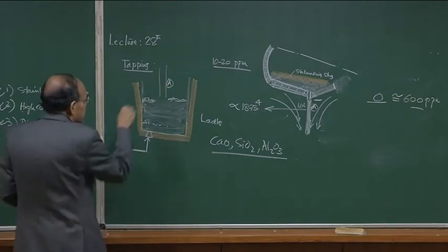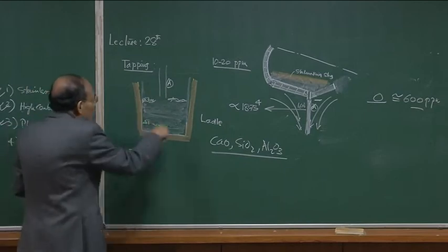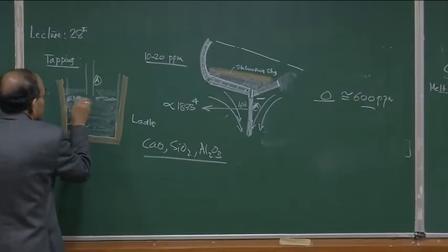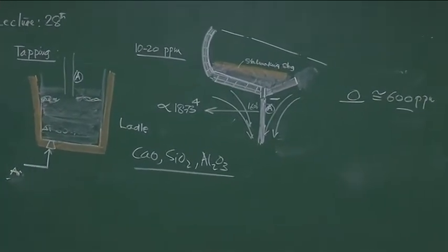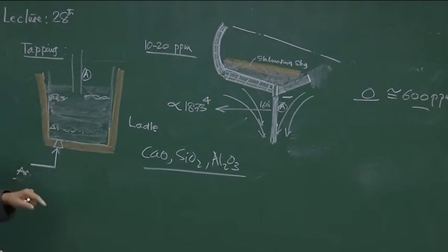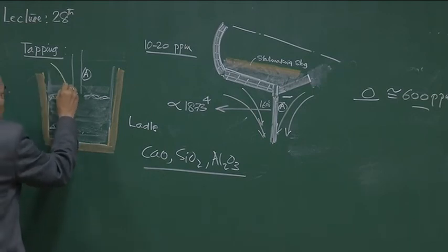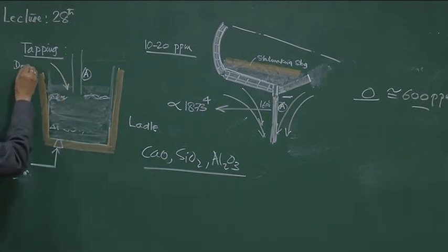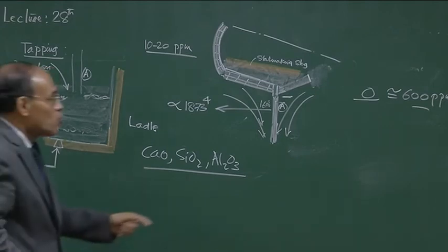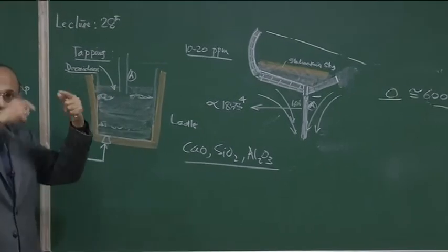So, the moment the furnace is tapped, tapping starts, the argon blowing is also started. So, there is a huge amount of stirring which goes on, which expedites melting, slag is formed, and after some time the ladle is ready to be taken. During pouring of the molten metal, once the ladle slag is formed and the metal is half filled, deoxidizer elements are added. The elements which have greater affinity towards oxygen and which will help us to reduce this oxygen are also added, and we want to take advantage of this intensity of stirring.